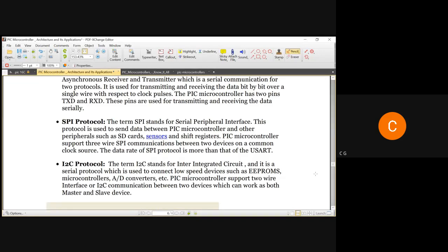Using this protocol, one master can communicate with many slaves or many other peripherals. That is the benefit. Each device has its own name or address, right? So this protocol will send and receive with that particular address. It is like asking individuals to do certain tasks by calling their names, right?